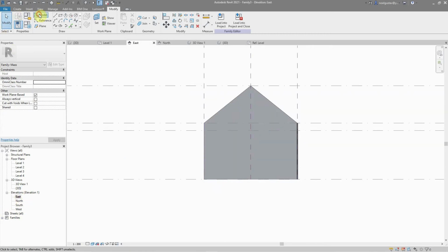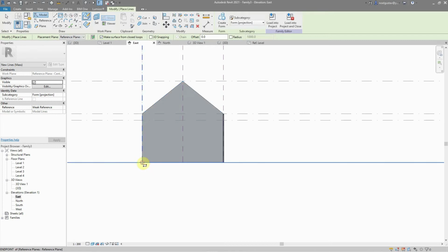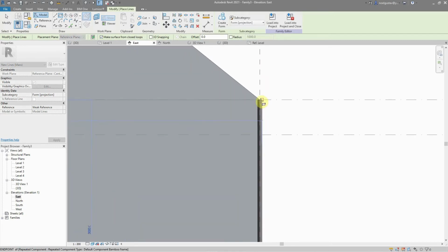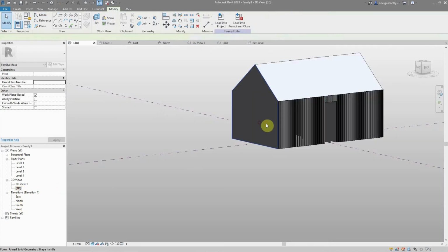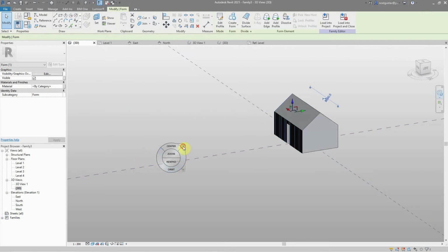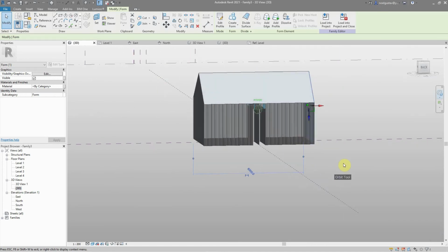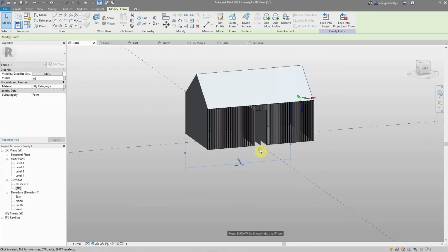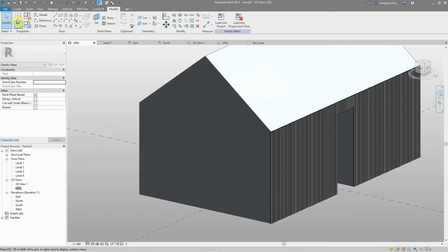And then this time I'm going to hit model, create, make surface from a closed loop. I'm going to hit this point, and then I'm going to hit this point here. So I've divided the area extra, and I can't see it. So it should be right there in the middle, but I don't want it to be there. So I'll simply do it in 3D view.